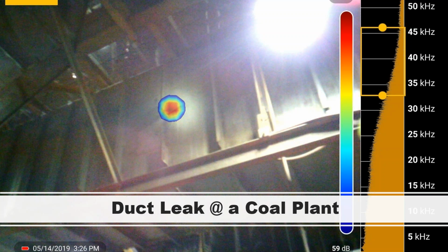And it's not just about pressurized things. Sometimes it's about vacuum lines as well. So look at your facilities and your customers that have vacuum systems as well. Think about the big vacuum systems that pick up large pieces of steel and move steel plates. If any one of those vacuum suction cups is not working properly, you could drop that steel plate and halt your process.